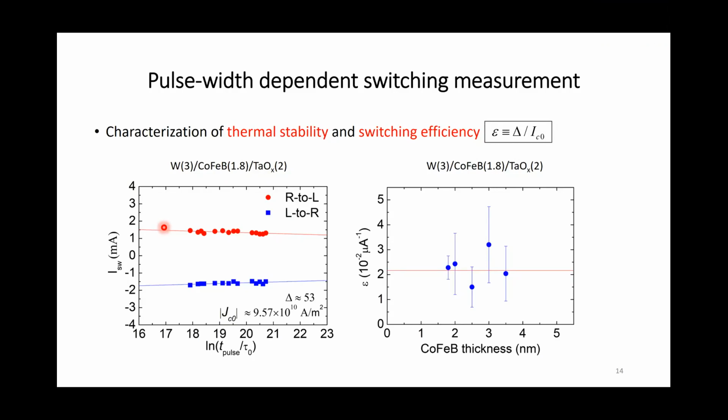I see. Okay. For the films prepared by E3, because they have much cleaner hard axis behavior, we can estimate the anisotropy field. From those films, we can estimate KU times, for instance, a specific subvolume or thermally activated region, and that product can give us maybe a more reasonable estimation of the thermal stability.